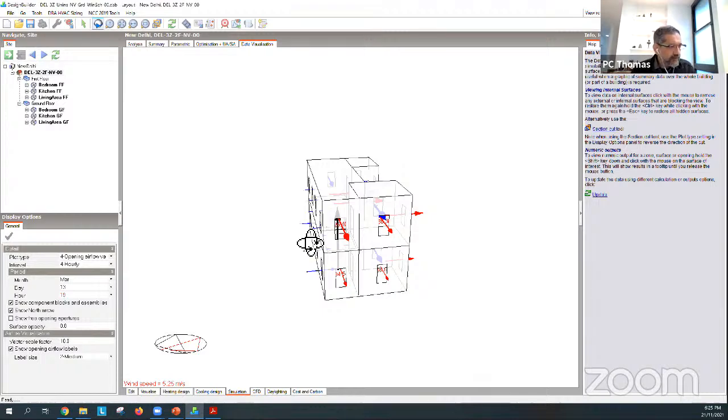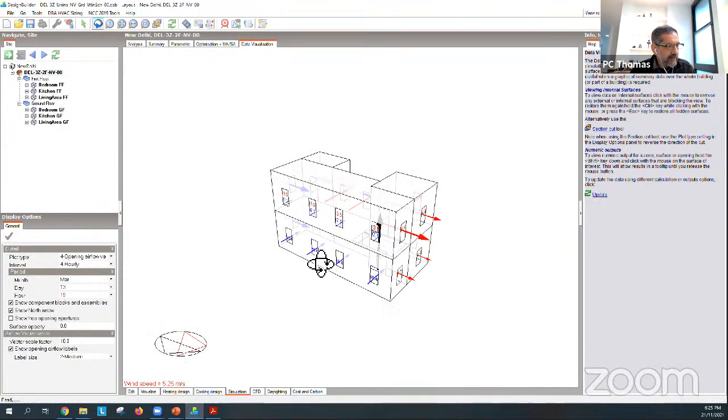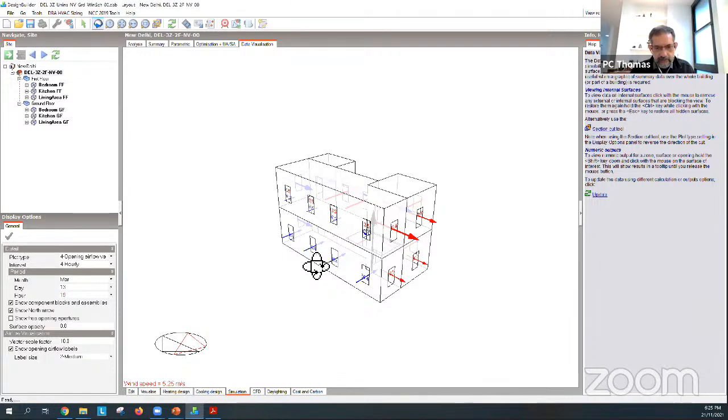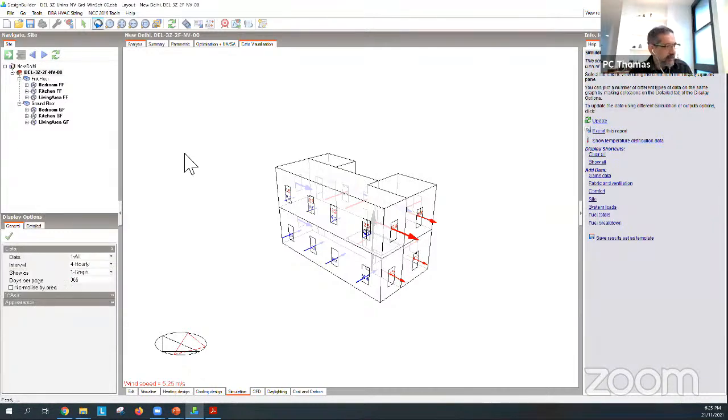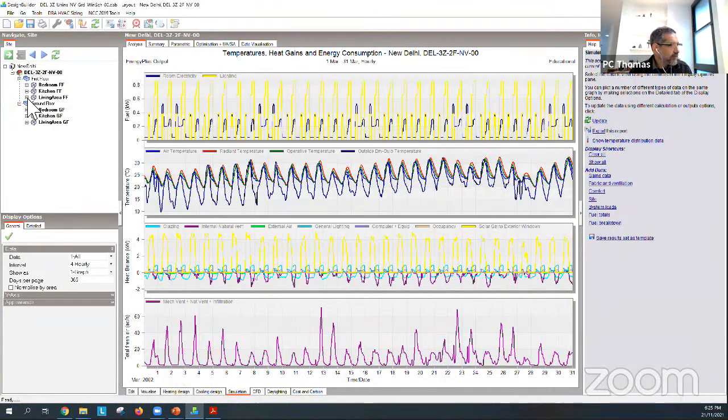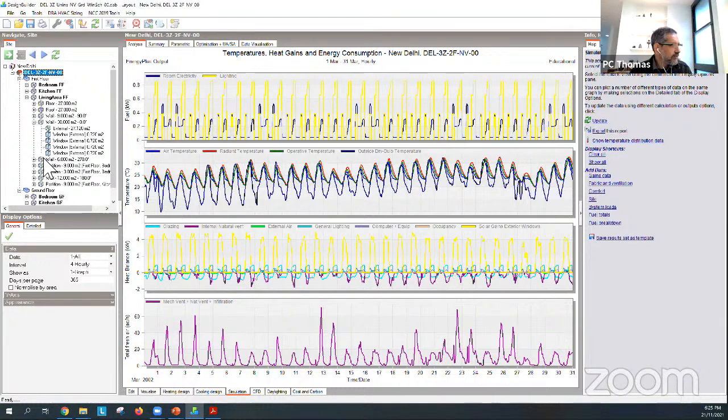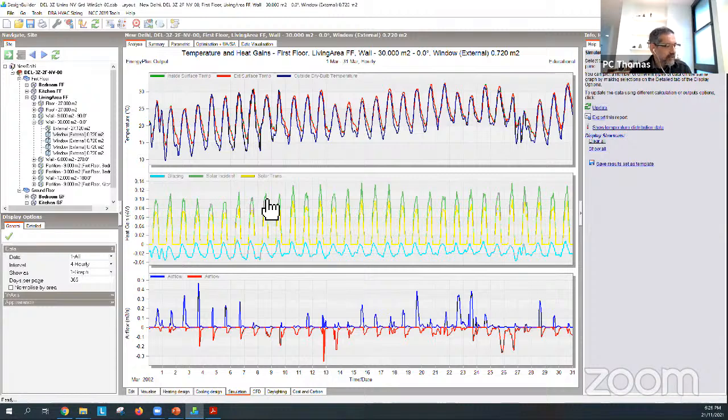Okay, now what kind of effect is going on? Okay, and you can look at that in a little bit more detail. So if I go back, still in the DesignBuilder interface, and I look at just a wall, the north facing wall, and one of the windows, it will actually tell me the blue is airflow in and the red is airflow out.